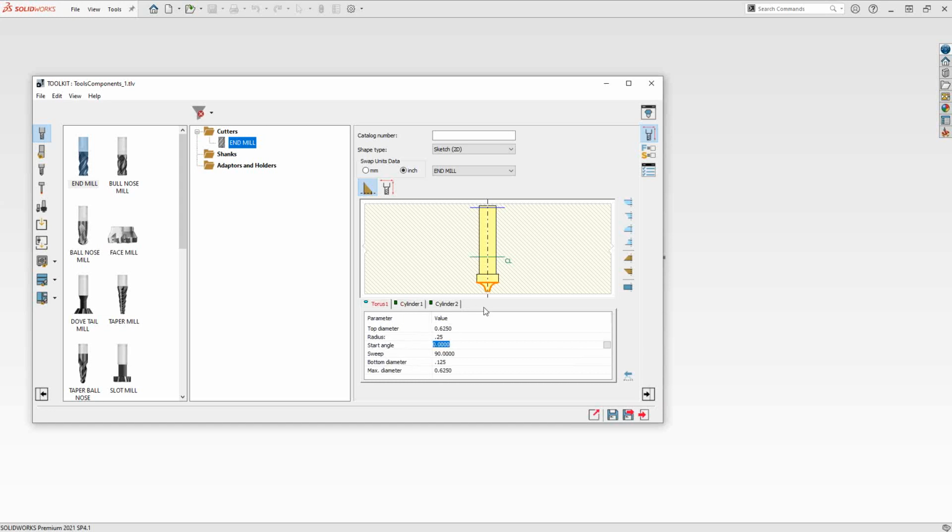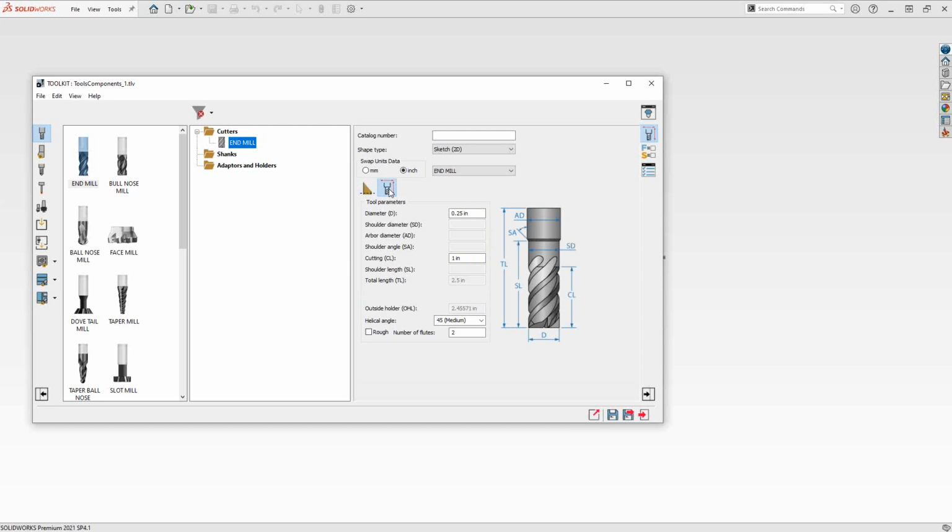Okay. By setting these parameters, you can see that these three shape items, the building blocks here, take that shape. If I bring it back to here, I'm still using the flat end mill definition, but now it's removed all the bits that are unnecessary, and we can give this some proper dimensions. I made my arbor 1/2 inch, so I'll make that 1/2 inch. My cutting length, let's just make it the actual quarter round bits. That will just be the radius.